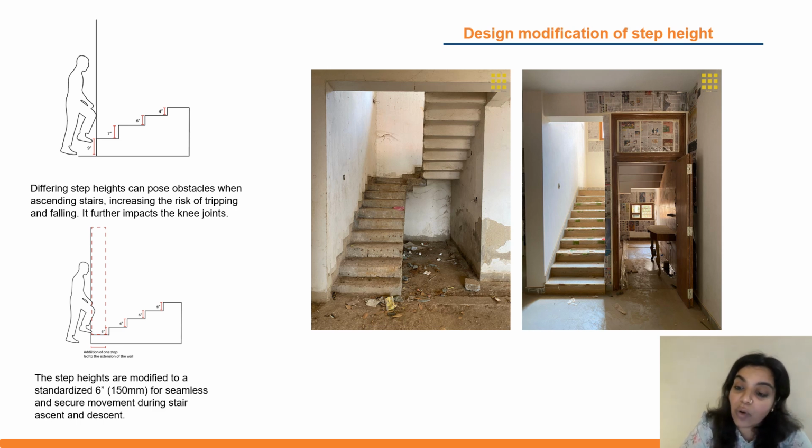This led us to a lot of discussion with our contractor, and we even heard things like most of the architects practice this. This is a regular practice. 7 inches, all right, and why do you think you want to do this? And we had to educate them about how important it is to maintain a 6 inch riser.